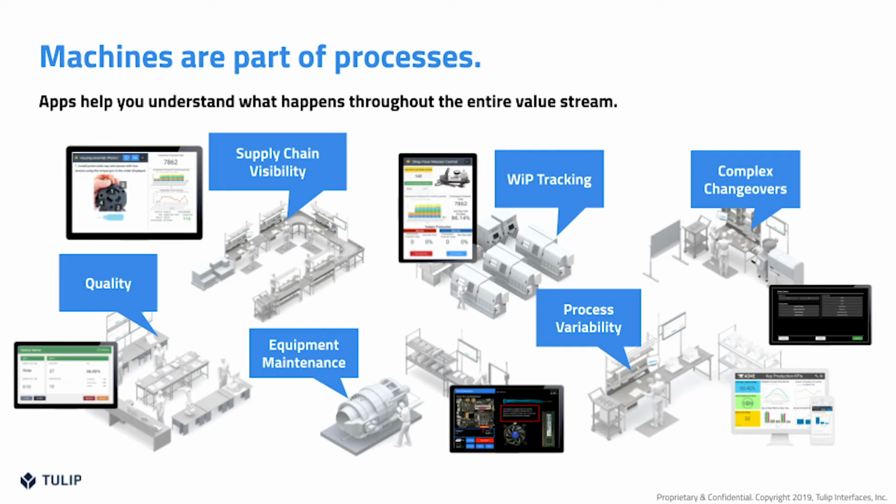Another great use case was cycle count machinery. For middle volume, cycle counting is always, once again, seeing downtime waiting for materials. If they have to restock certain cartridges on the machine, they can see where those cycle counts are and tweak the machine monitoring outputs to see where they can maximize. If they're changing out cartridge 1 every 200 pieces and cartridge 3 every 400 pieces, maybe they could do a tooling change so they're both on the same timing and the downtime isn't broken up as much.